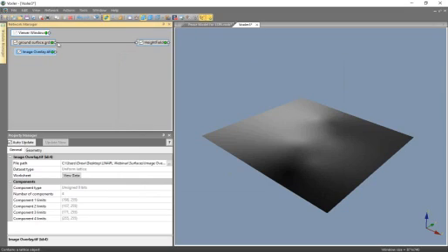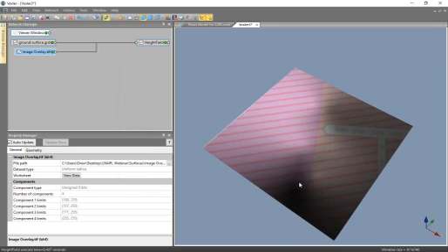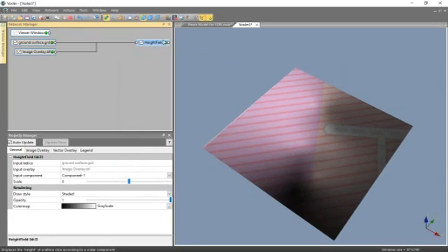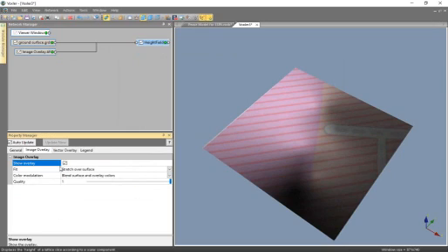And to drape or overlay this surface on the height field, I'm going to need to drag the connector from the TIFF over to the height field module, and then choose Connect Input Image Overlay from the context menu. Okay. So I rotate this down. You can see both of the surface color and the overlay color are blended together. So I'm going to account for that right now by selecting the height field, moving down to the Property Manager, and on this Image Overlay tab, we can see that our overlay is being shown clearly. I'm going to change the fit here to Clip to Surface.